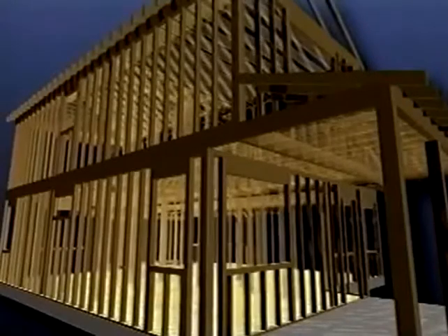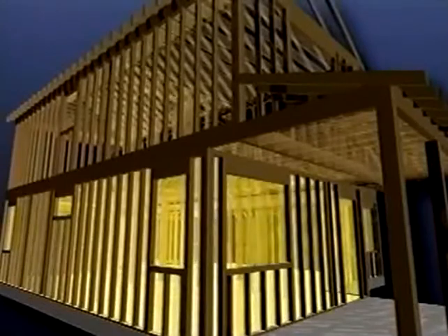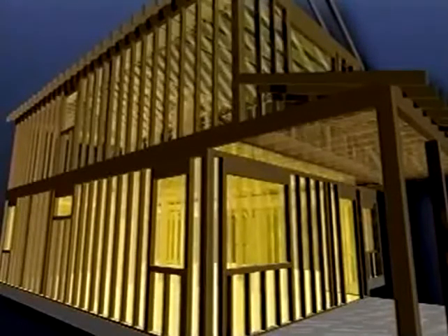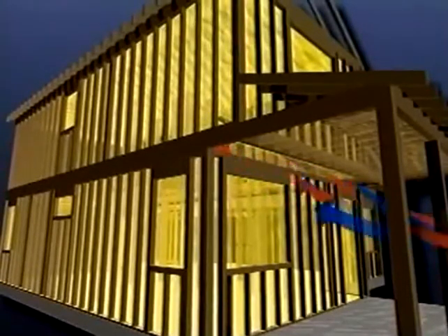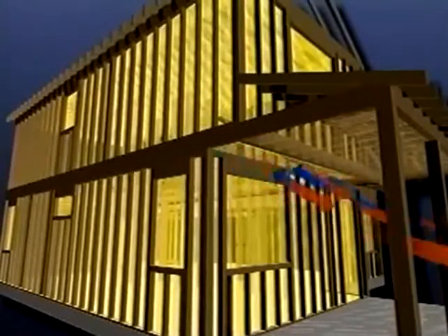As we've said, in order for the air barrier to work, it must be continuous. Holes, no matter how small, can allow indoor air to leak out and outdoor air to leak in. Here in the southeast, one of the reasons that we're concerned about air infiltration is because of humidity. Bringing that moist, warm air into our homes is really one of the reasons why we have air conditioning, to create comfortable living environments. And of course, we also know there's other things in the air, such as pollen and allergens and outdoor air pollution that's coming into the home.